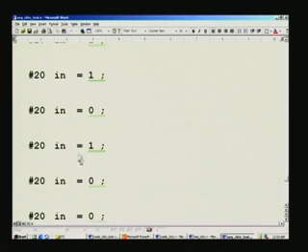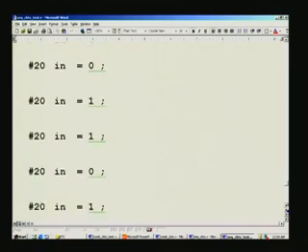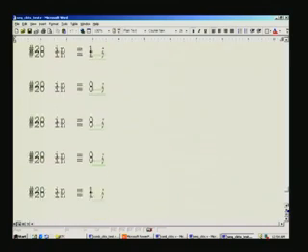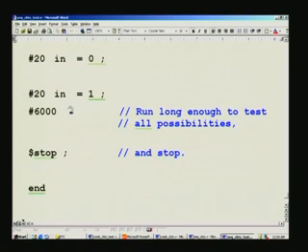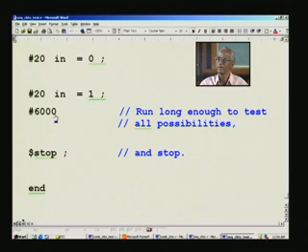Every 20 nanosecond I am changing the input pattern as per the pattern that we have already listed earlier. And once again, this being a sequential circuit, you give more cushion. Arbitrarily I gave this one. After running the simulation you will know that it may not be required. So, you can always come back, change to what you want, thereby quicken the simulation process, but it is hardly noticeable for these values.